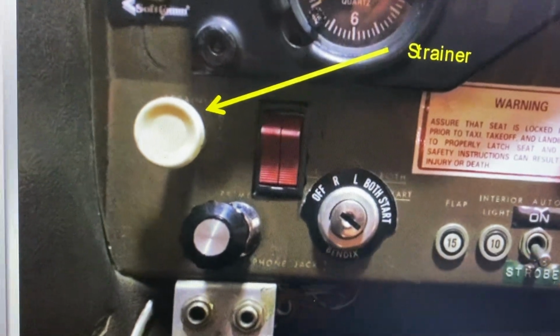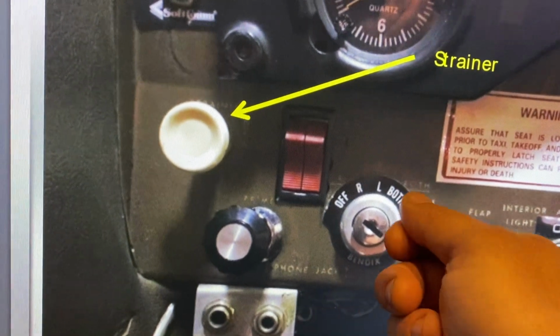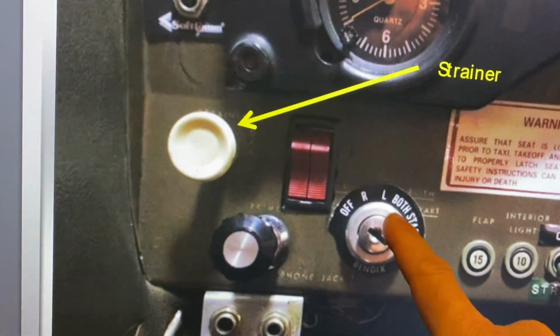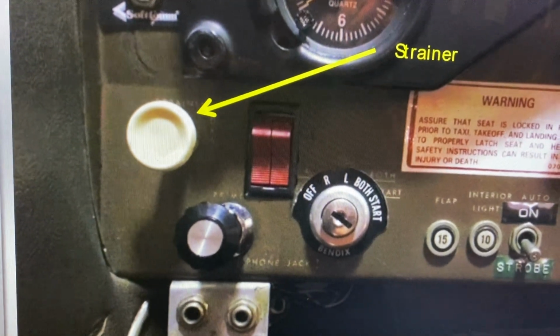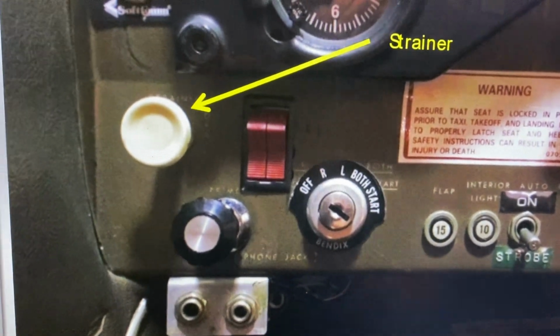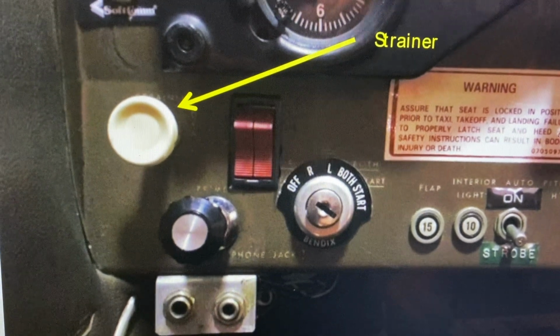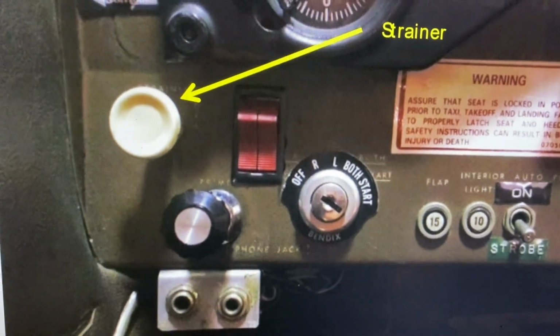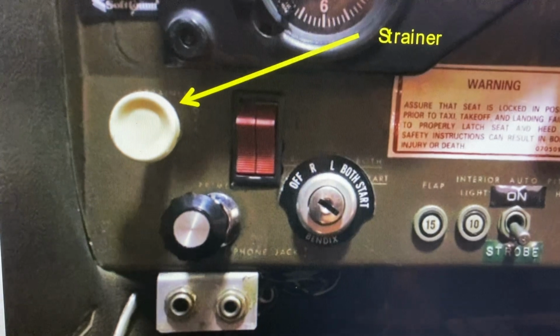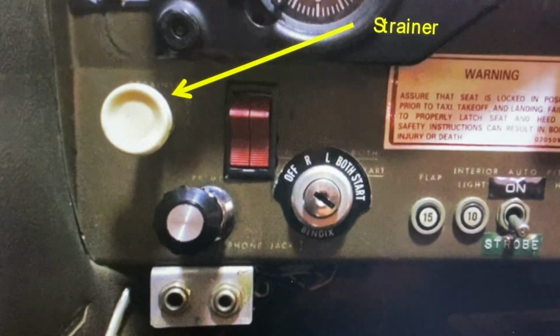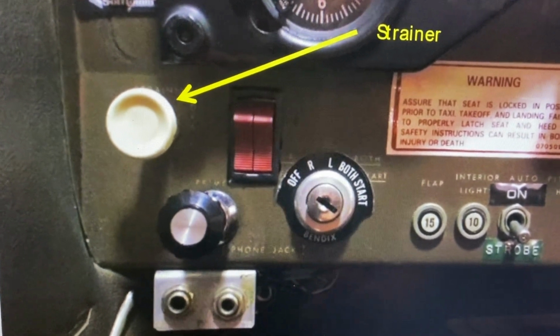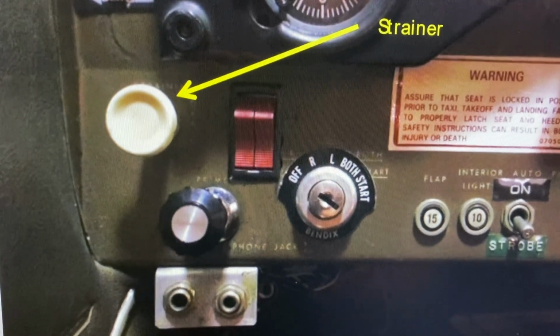And what you're going to do is run the engine at 1700 RPM, and select left mag, L, first. And you're going to note that you lose a little bit of RPM. The reason why is because the engine's not going to be running on both magnetos anymore. It's only going to be running on one magneto, so it's only going to get one spark in each cylinder. And it's always more efficient to get two. So you're going to lose a little bit of RPM, but not a lot. That's what they call a mag drop.